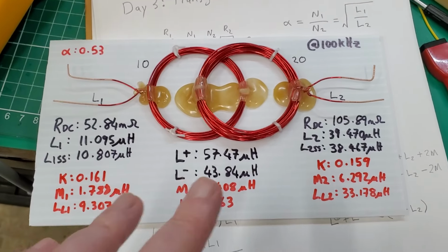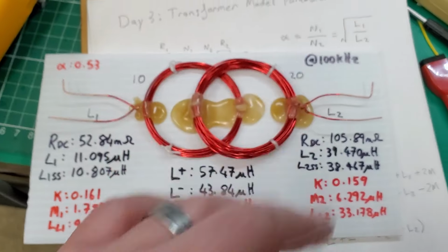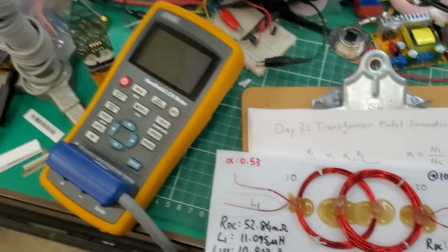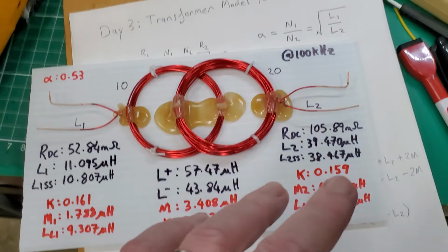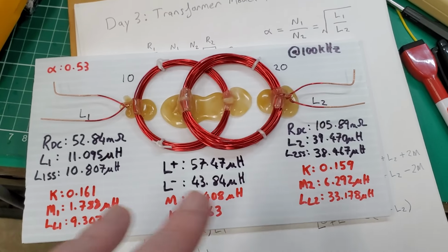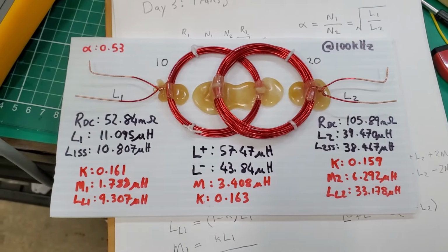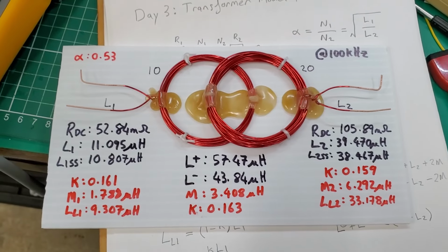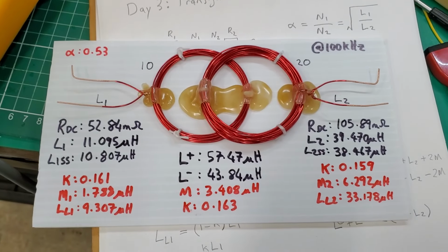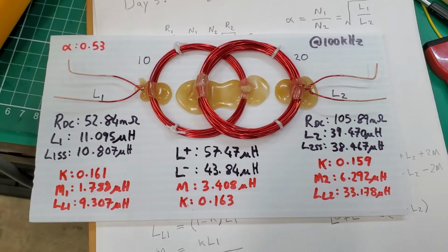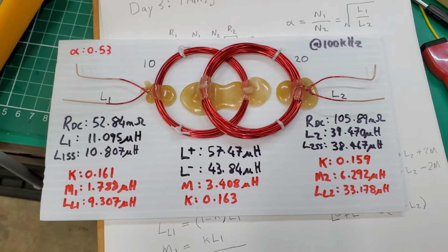I don't know, again, if this is measurement error. I had to measure this transformer at a higher frequency, at 100 kilohertz. I don't know if my bridge is kind of crappy there, or if the distributed capacitance and other things are starting to become an issue. To do this properly, obviously you need a more sophisticated model, but again, we're kind of limited by our very straightforward model here, where we're just assuming it's lumped inductors with a certain amount of linked flux.